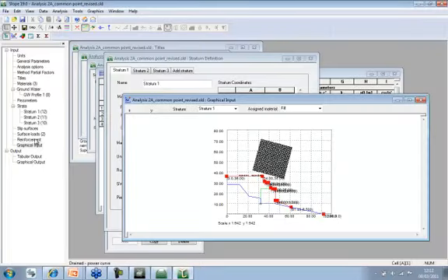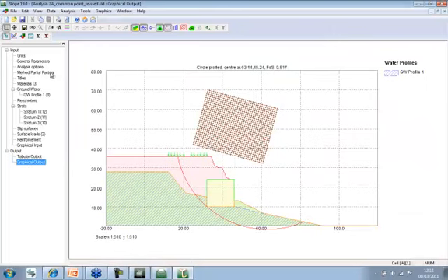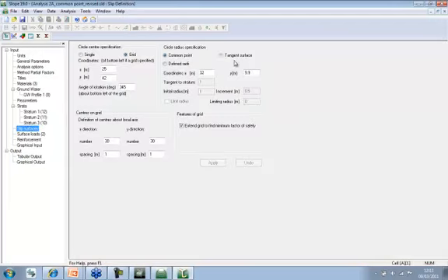So if I just go, and as you can see, we've applied 2 surface loads here as well. If I just go to graphical output, this will help you appreciate what Slope does. After I've run an analysis, it just chooses the worst case slip surface through the common point that I mentioned. So the slip surface was selected to go through a common point, which is the same coordinate as the back of the reinforced soil block.